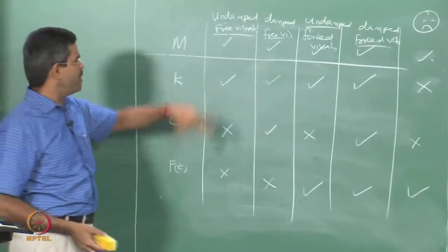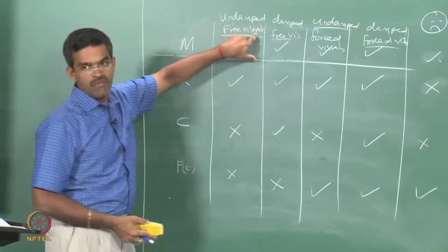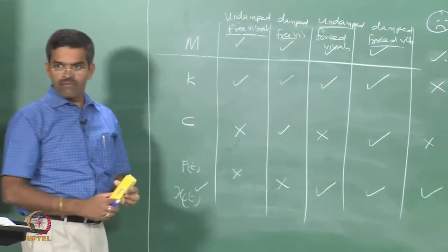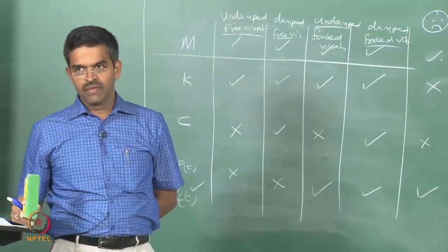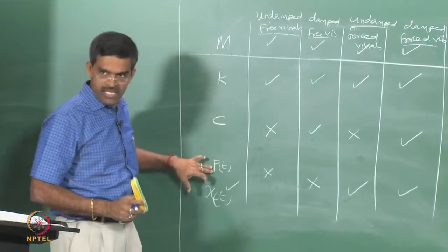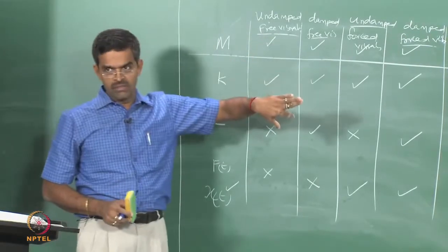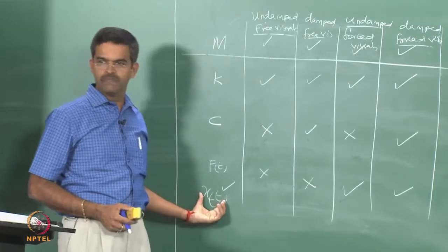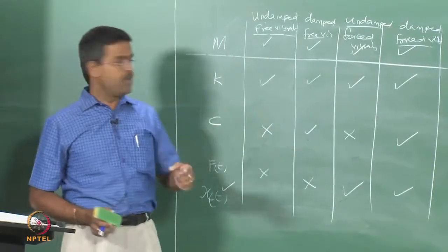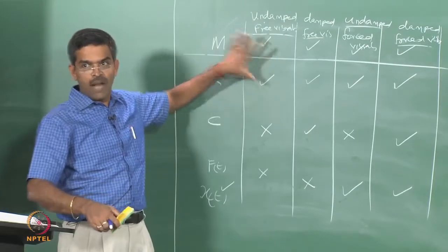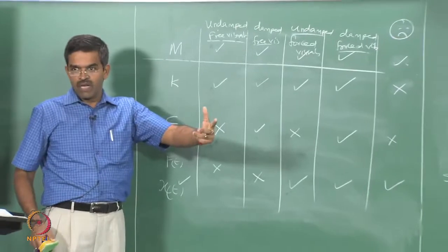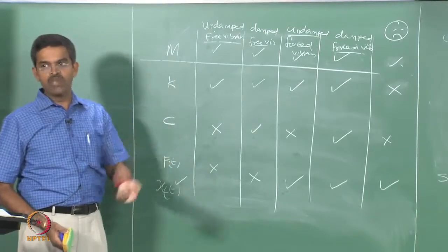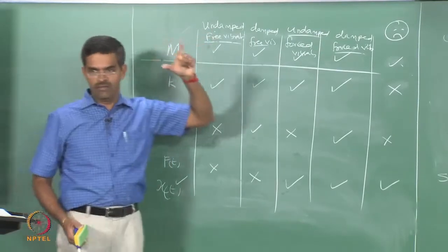So, for making it very easy, we must start with the system. So, we look for undamped free vibration model. What we are interested in? To find x of t. Why? We are interested in dynamic response analysis. We already know, using these 4 characteristics, if I form an equation of motion which is an ordinary differential equation and solve it mathematically, I will automatically get the solution. Okay, just now we saw that. So, we will pick up an example, write equation of motion, apply mathematical concepts to that, solve it as an ordinary differential equation, get x of t and try to understand qualitatively what do you mean by response analysis of undamped free vibration model. Is it clear?